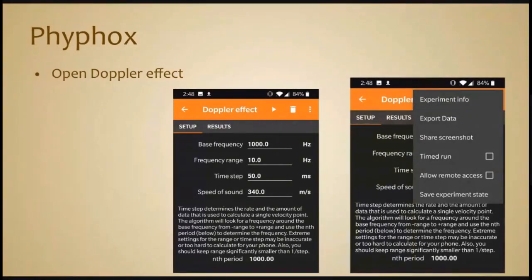So the final result would be 1000 plus 1002, that will give us 2002 divided by 2, that will be 1001, a very high frequency. The other one is the difference, that will be exactly 1 hertz, like 1002 minus 1000 divided by 2. Now, after taking the product of the two sinusoids, you will have a high frequency component, close to 1000 hertz, and you have a very low frequency component, 1 or 2 hertz. Then what you do is you pass the entire thing through a low pass filter.